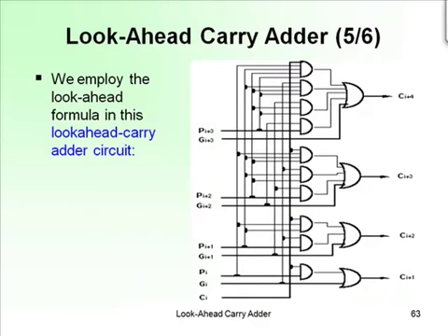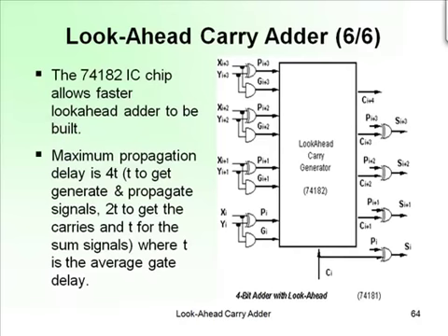So this is what an actual look-ahead carry adder looks like, and you'll probably see more of this in computer architecture. You'll do the look-ahead stuff, and you can see here that this thing is going to add a lot faster than a ripple carry adder, because based on the fact that it can tell whether it needs to propagate immediately upon the inputs, when it's calculating bit for bit what's going to happen to the next bit. So this is just another pictorial representation.